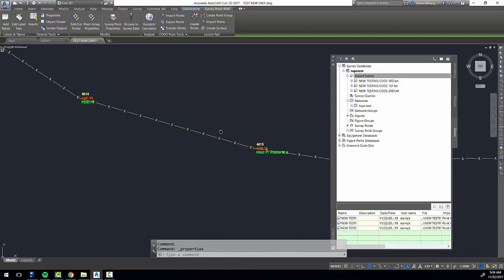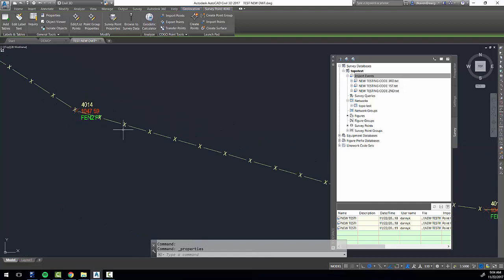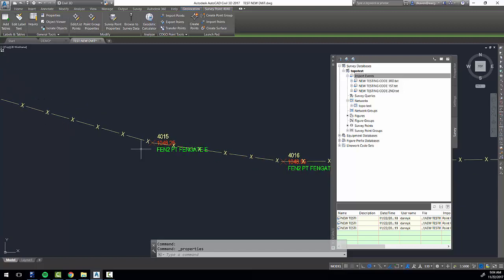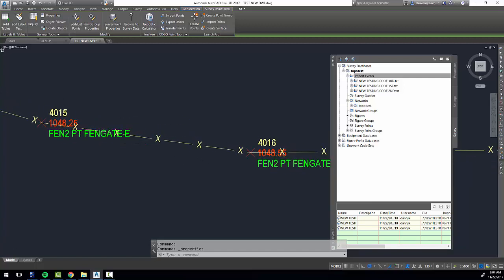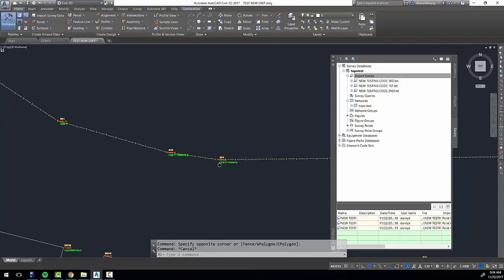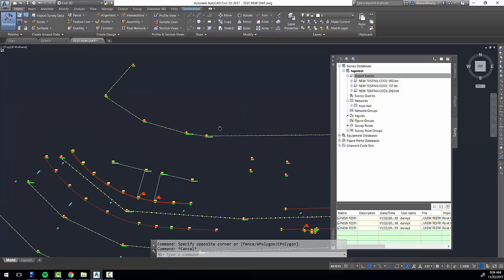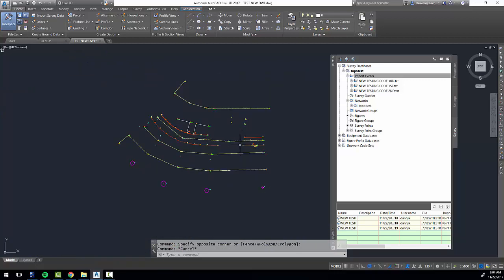Same goes with this fence. So we've got our fence, fence 2 code running. These are posts. And then we get up to this area here, and there's a double point here, or a 1 point double code. So we've got a fence post and then the gate. So you can see right here without a doubt that, hey, in between these 2 points, that's where the gate is. Maybe there's sidewalk running off of that as well, so you can code it up. Anyhow, that's what we've got.